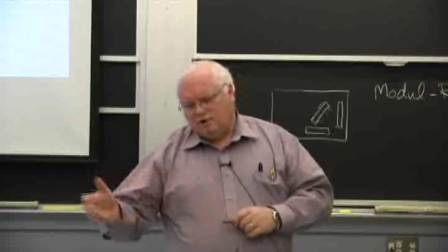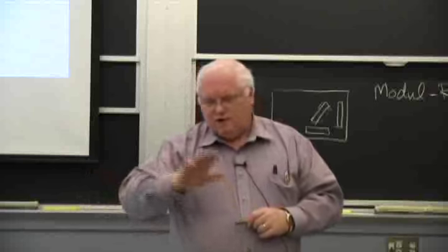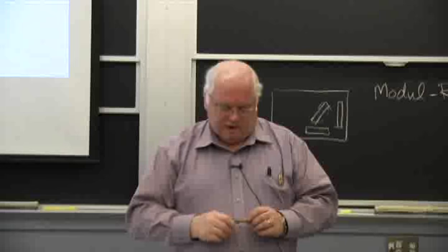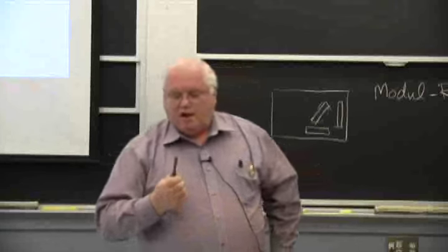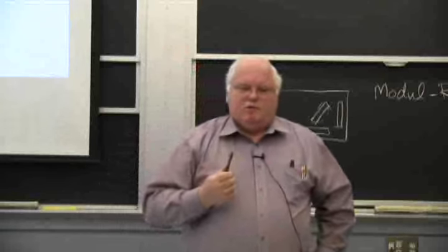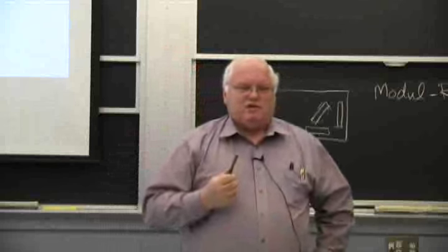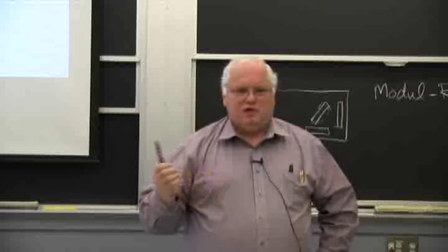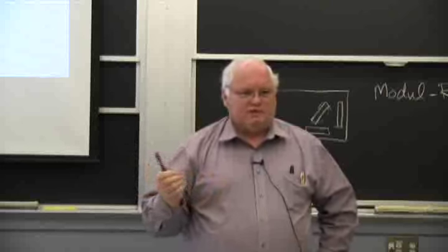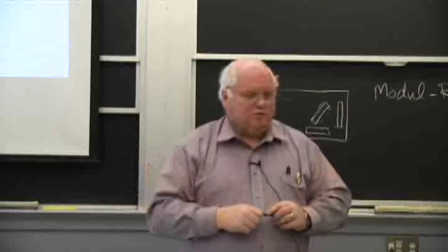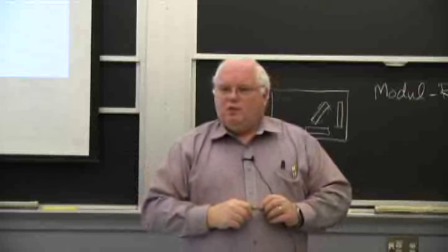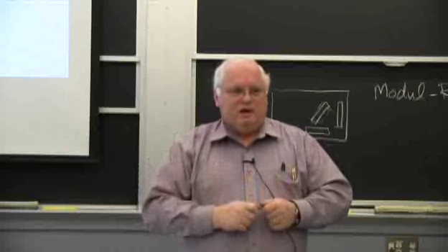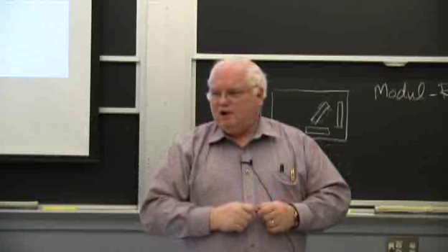And so I explained to them what it was, and if you take my welding module and diffusion bonding, you'll hear about that, and I may tell this part of this story. But in any case, they said, well, we actually have tried a 65% copper, 35% gold, 3% nickel alloy. Obviously that's 103%, but I can't remember where the 3% was. And we get very good results. In fact, we can bend it 180 degrees on itself and it doesn't break.